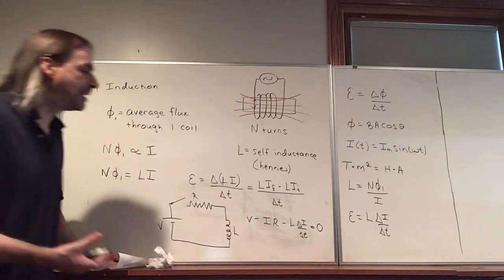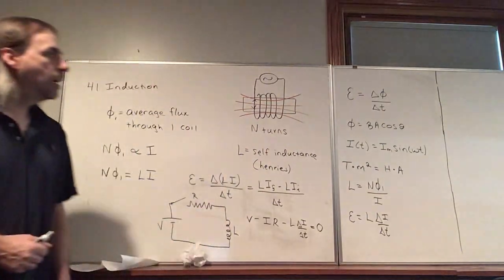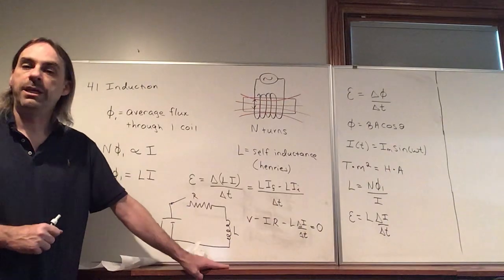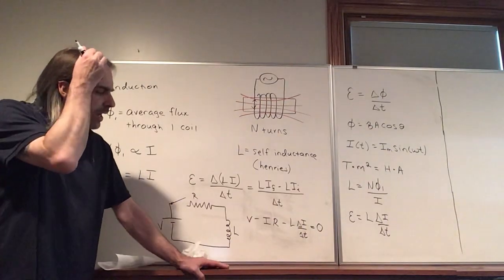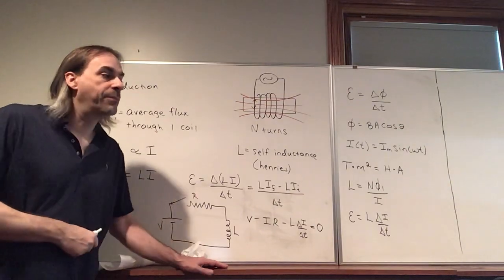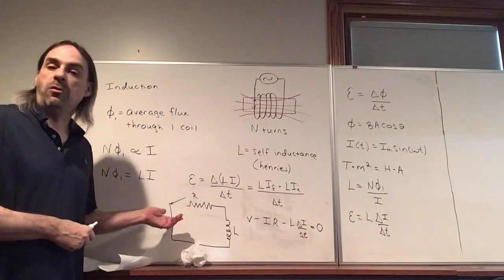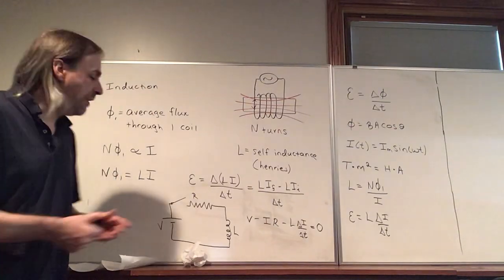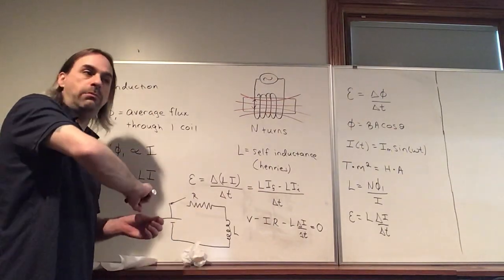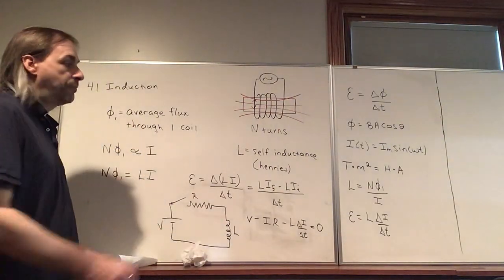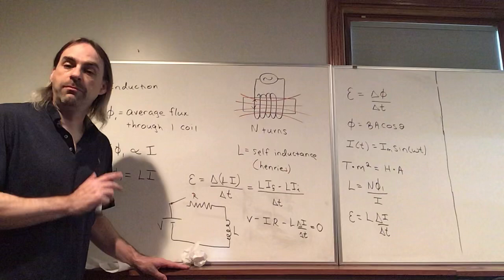Just the concept that the greater the inductance, the more resistance there's going to be to a change in current. And that's regardless of what type of current you're dealing with. So if you had, say, an adjustable power supply, if you have a certain current going through there, if you try to increase the power and increase the current, this inductor would oppose that as well. So it's not going to stop it from happening, but it will slow it down.